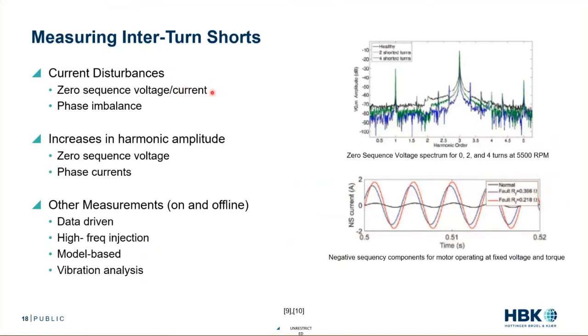So we can look at that zero sequence voltage or current. And in my example down here, I have normal operation of zero sequence voltage where we see that black line, not a big sine wave. And I have a couple different faults, and we can see a really big zero sequence, or negative sequence voltage and current. So this is pretty dramatic. This is a really good indicator, and we can watch this creep over time. If we start to have a little short, we can see this, and over time is relative, but 50 seconds before a major fault, you can see that start to creep.